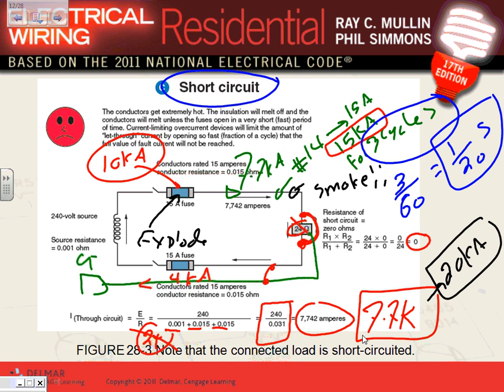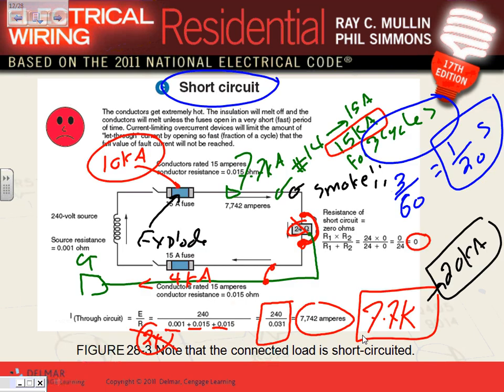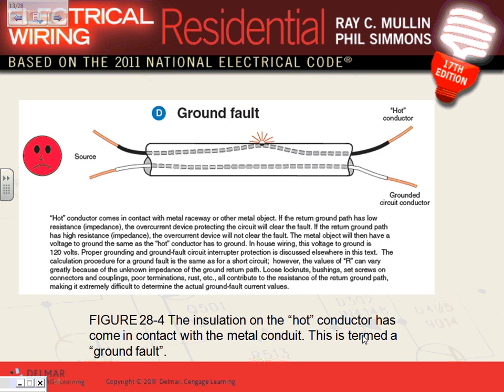How do you get a ground fault? You take a phase to a conduit, grounded. A phase to the neutral, grounded. Anything that's grounded gets you a ground fault. Okay? So the reason why, if you size for the short circuit, then are you covered by the ground fault? 95% of the time you are. So that's why we worry about this circuit, not this circuit. You can use the same impedance, guys, because if you do a ground fault, the impedance could be higher in a ground fault than on a short circuit.